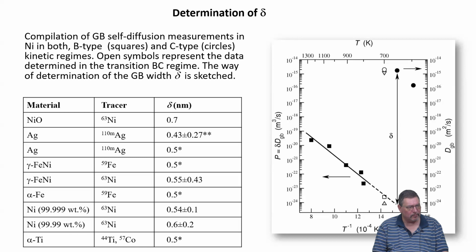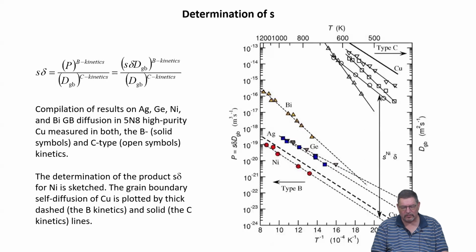If you know the grain boundary thickness, you can also determine the segregation factor, right? And this can be very useful because otherwise it's very difficult to get this value in a quantitative form. Any microscopy has difficulties because grain boundaries are too thin. And atom probe tomography along boundaries is something very difficult because of rupture of the sample.